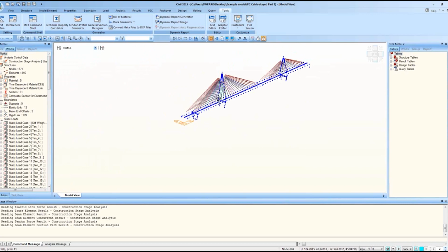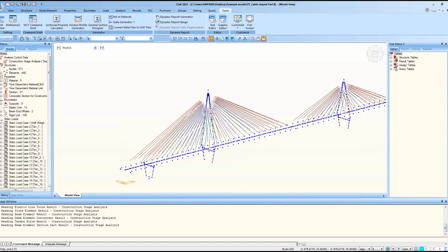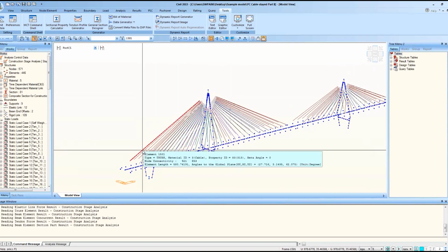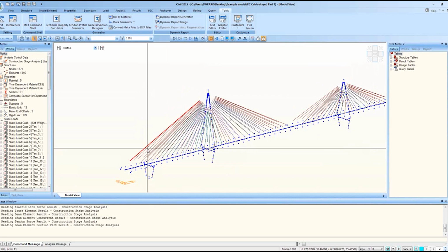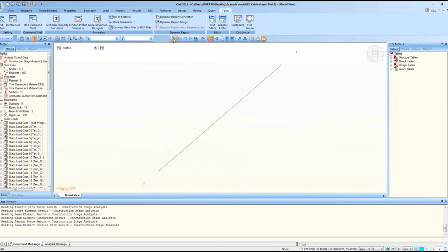Also, you can use the element selection and element activation. So how can you select your element and node? This is a single selection, for selecting a single node or element. Once you click this one and select one element here, it is highlighted in red. If you want to just see this element, activate it using the Activate button, as you can see here.